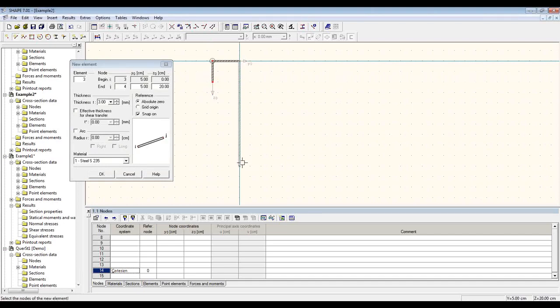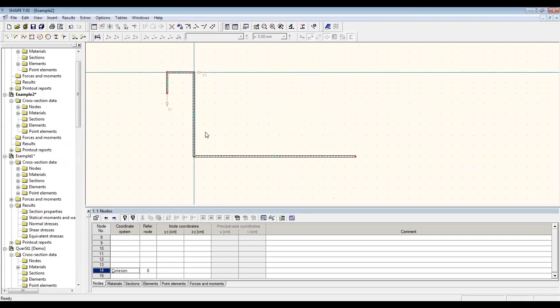I want the height to be 16 centimeters. And then the width of the trough I want to be 30. And so, because I have my reference, you can see in the dialog box my reference is at absolute 0. If I change it to the grid origin, so now this is the 0 line for Y, I can go ahead and place it at 30. Okay. And since it's symmetric, I can just do manually 1/2 and then make a copy of the rest over.